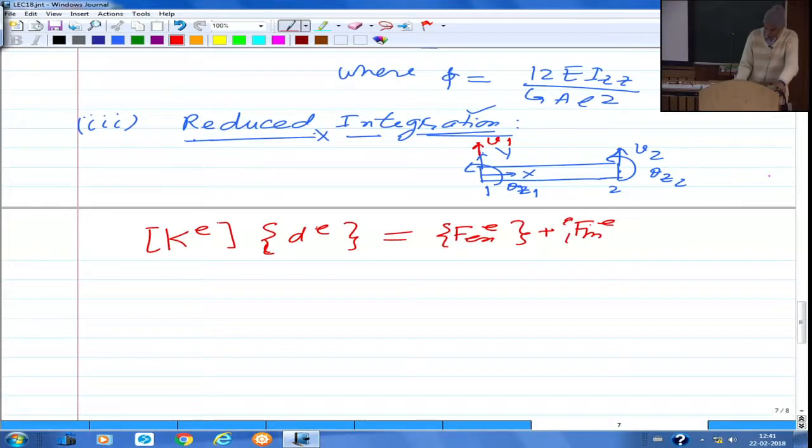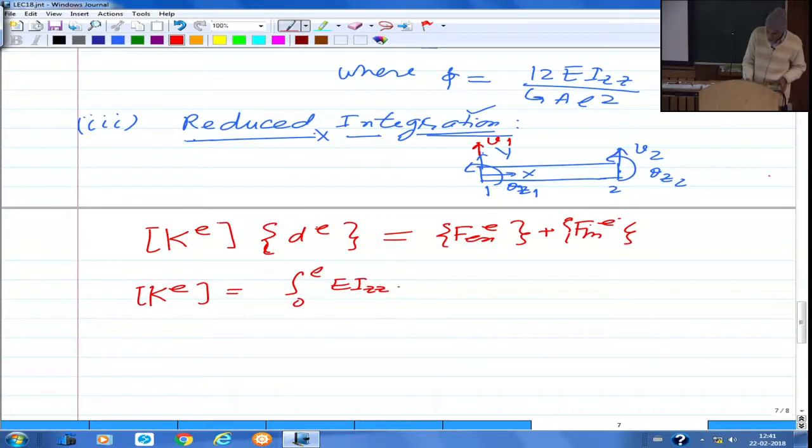and if we take out the axial deformation part, the stretching of the centroidal axis or the neutral axis, then this term would be simply EIZZ into the B matrix, only the theta z part of that B matrix. So let me still put it as B transpose B into dx. So this was coming from the bending. I have just taken out the axial part. So this is what you will have if you are only having the bending part, no axial deformation, no axial load.